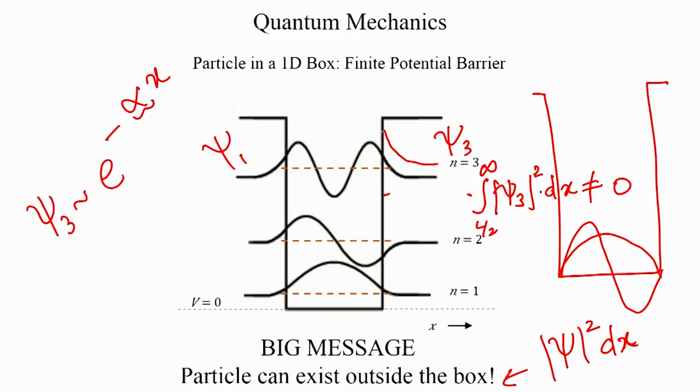The source drain regions are doped so as to encourage the injection of carriers through a mechanism like this in a MOSFET, okay. If you have heard of something called a scanning tunneling microscope, that too works on the principle of trying to measure the electrons that have escaped the well and are found inside a barrier, okay. So this mechanism of getting the particles to go through the barrier, if you imagine the wave function is going through the barrier, despite the fact that E is less than V naught, this mechanism is called tunneling, okay.